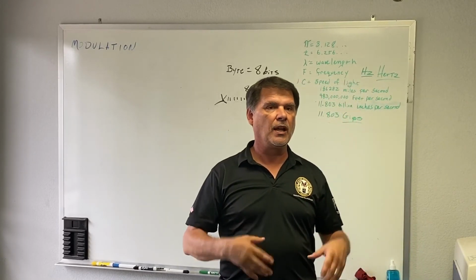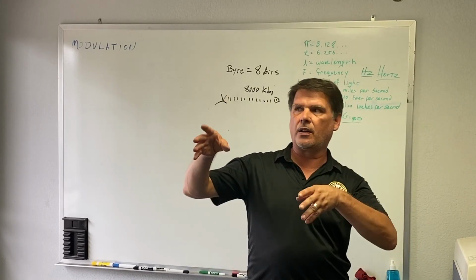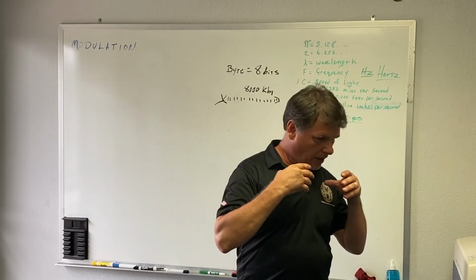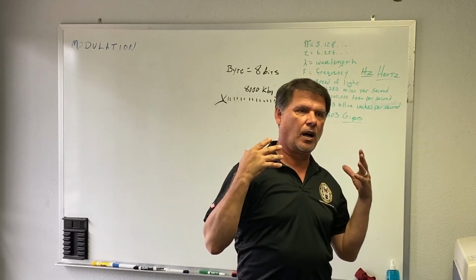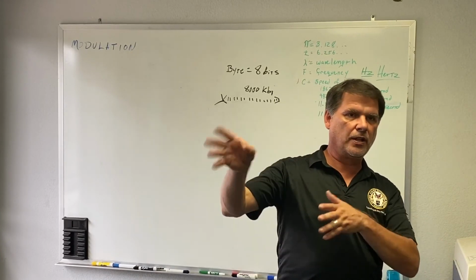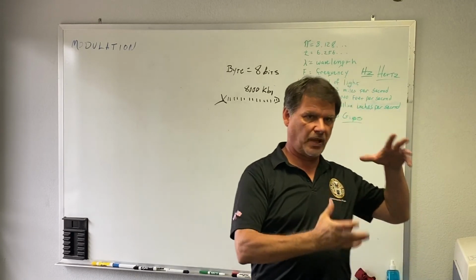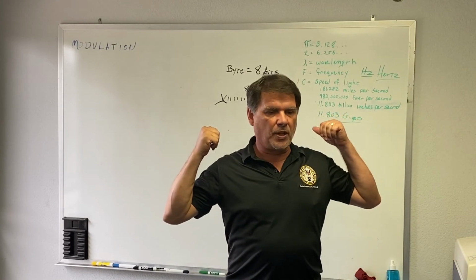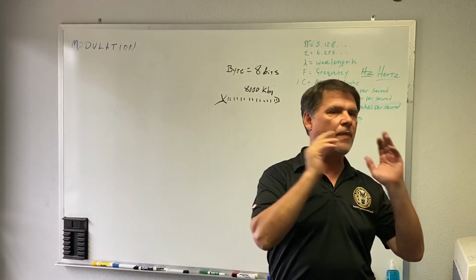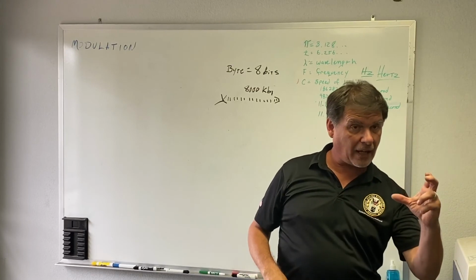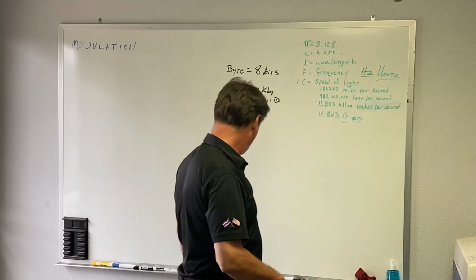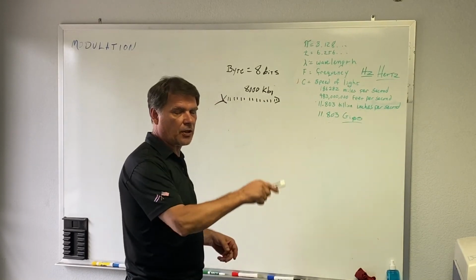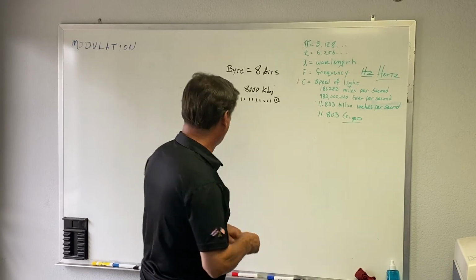But what more typically happens is inside the repeaters, the repeater demodulates the data, and then it puts it through basically a Mac chip. I don't know if they use Mac chips specifically, but what these do is they have big FIFO buffers. And so they just basically stuff all this data in, and then when they're ready to burp the data out, they try to burp it all back out, but it may not all come out the same order. But all the packets will come out. What they do to stop this problem at all, and this is the same thing in Ethernet. It's the exact same function in Ethernet, in wireless Ethernet, it's the same function.